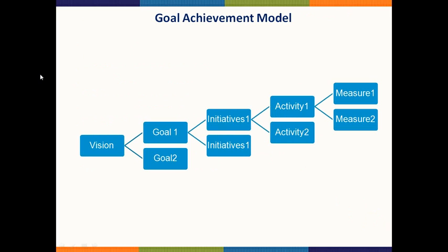If increasing reliability is your goal, then maybe you will have RCM, CBM, maybe you will do TPM, or whatever the initiatives might be. And for each of those initiatives, you will have different types of activities. Each of these activities in turn can have two things. One is the outcome, the results of those activities. The other is how well you are performing those activities. So that's the monitoring of the execution and then monitoring of the outcomes itself.